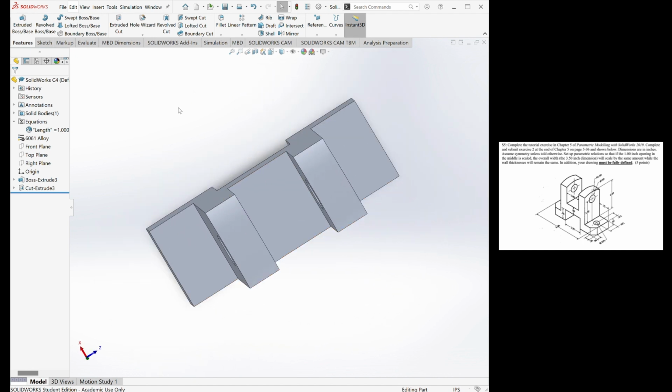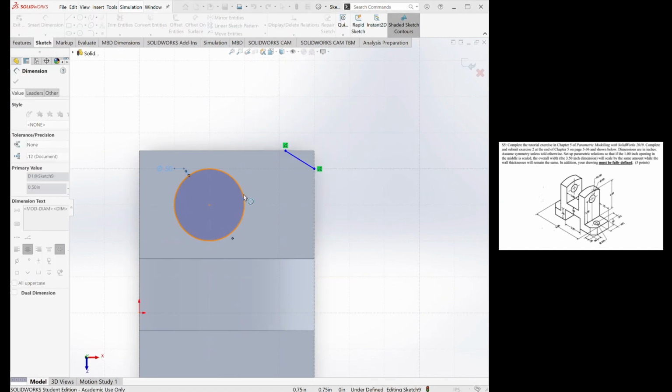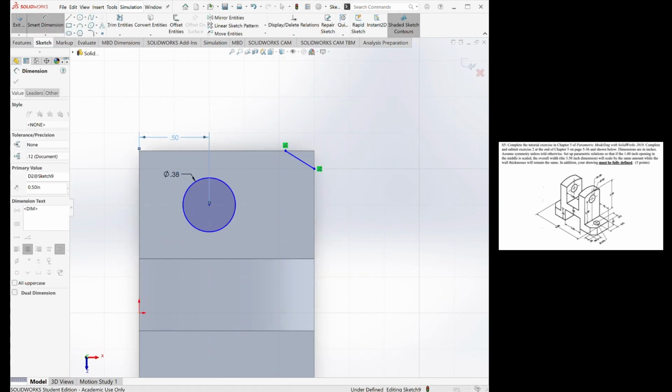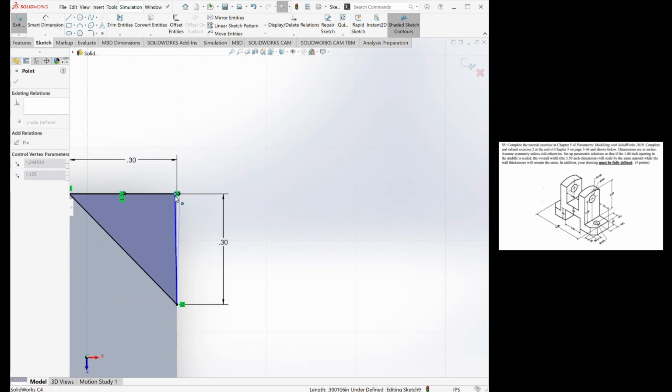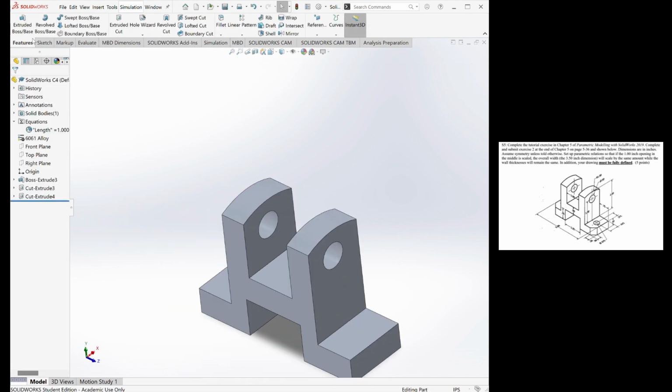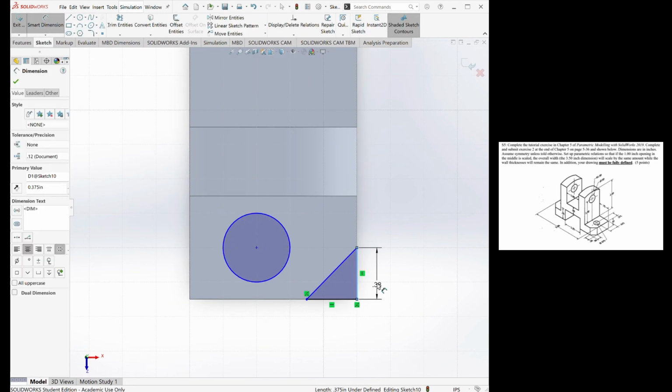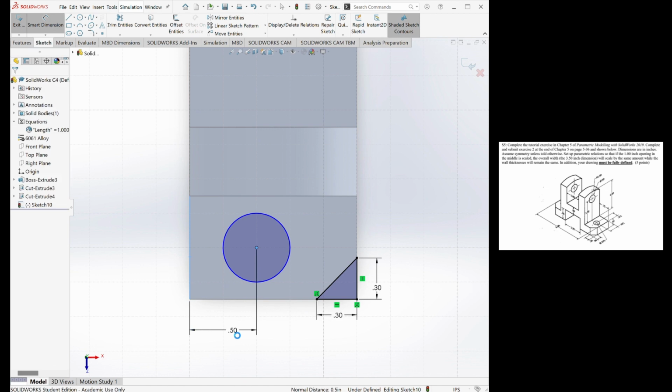Now we're going to make the holes and little chamfer type of features that exist on the faces on the bottom of the part. And we're going to do that as 2 separate sketches rather than one, again, so that nothing breaks when we move it. So I'm just going to quick skip over. By now you should be able to do all of this.